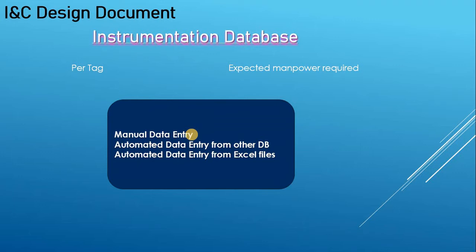Now, if you have another database like the process one, they have the process lines in the database for their Smart P&ID. You can import the same table of P&ID list, of line list, and all those things from other databases into your database as a table to select or to use.